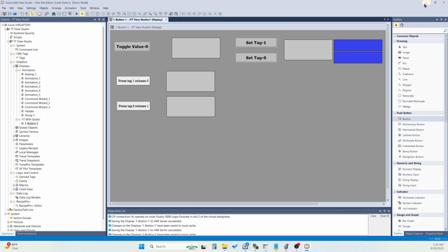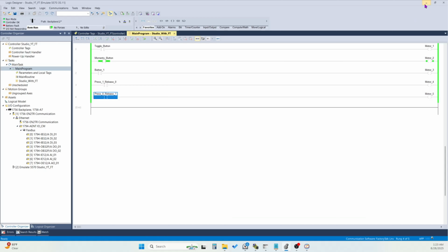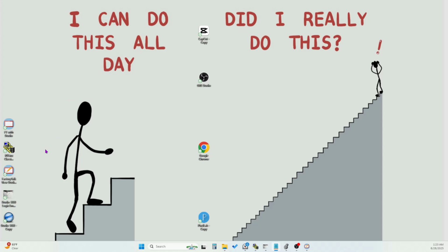I already created the runtime, so I will not create it again. If you created the runtime once, you need not create it again and again. You can use the same runtime, and whenever you change something inside of SCADA, run the runtime and it will reflect automatically. If you are changing some display setting, you can edit directly. And if you don't know how to create a runtime, you can see my latest video, how to create a runtime in 30 minutes. So double click on runtime.